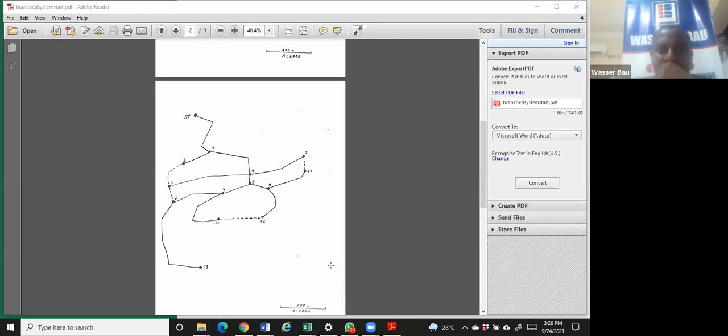Somebody says, what is a node? Well, a node is more like a manhole. That's a good question too. I want you to imagine a node as a manhole, where two pipes will meet. If your surveyor is taking his level every 20 meters, it means you can establish a node after 20 meters. If he's taking his level after every 50 meters, you can assume it's a node. It's just a reference point where the elevation details are known. What it does is that it helps you to calculate your slope.